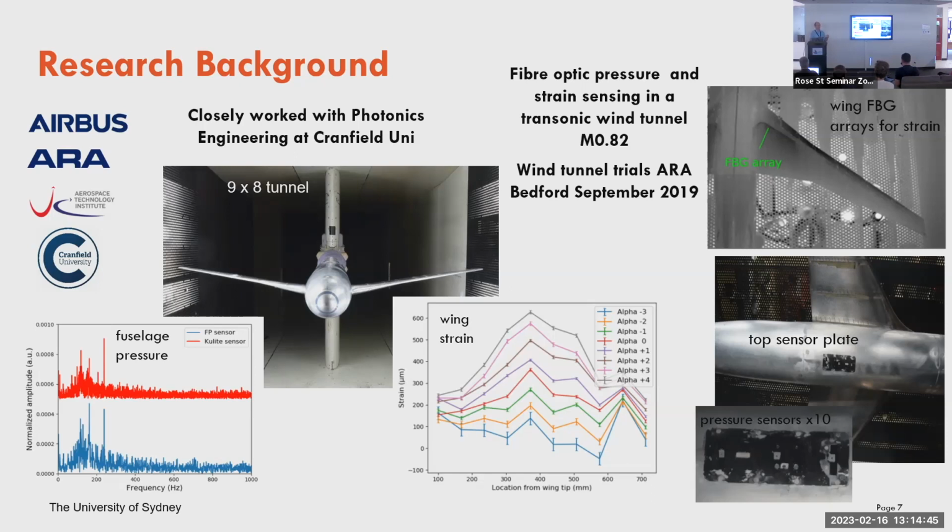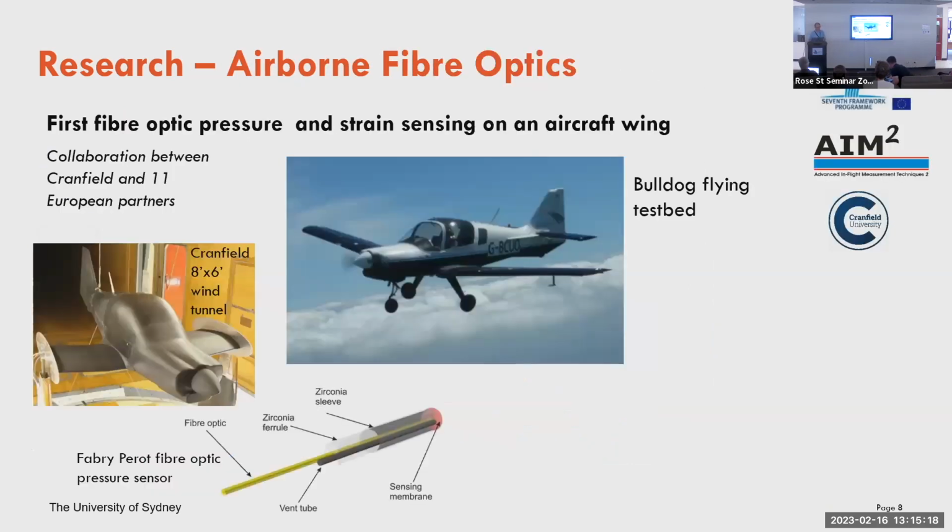But the big thing with fibres is they're always sensitive to temperature and something else. So you end up spending a lot of effort trying to correct because one thing's affecting the other. That's a common problem with fibre optic technology. All sensors have some sort of temperature dependency, but the fibre optics are typically very closely coupled. We have Niels here today, who's a big man on fibres, so he would know that, and we could talk all day about it, Niels. The corrections you have to do with fibre optics. One case in point is we flew some fibre optics on this aircraft at Cranfield. I'll talk a bit about that towards the end of the talk.